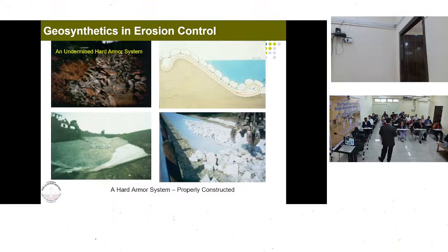You have a barrage, you have an offtake canal. Now, at the offtake canal, a lot of the sediment load, or the silt load, is being reduced. So in the canal you have relatively cleaner water. But the canal in itself has to come into regime. In order to come into regime, it will pick up the sediment load, and that picking up of sediment load will lead to erosion in the canals. Got it? This is a classic case which is currently occurring in Farakka.